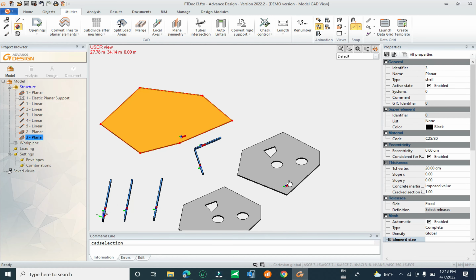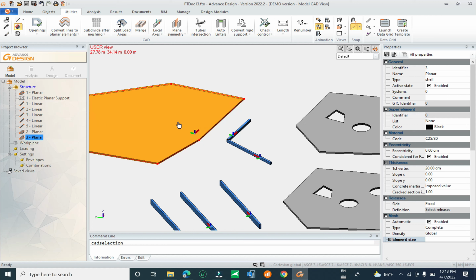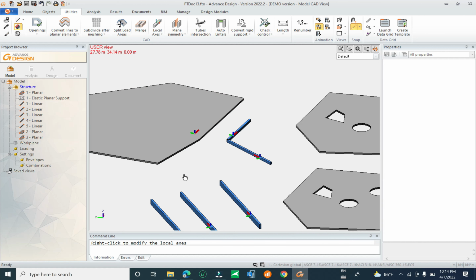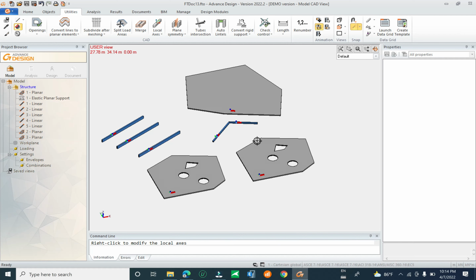Okay, in the same direction in x and z: local RC x, local RC z, local RC x, local RC z, and local RC y. It is the best practice when you analyze the complete model, or there are two or more elements in the same model. You have to make everything the same. It is easy to analyze and to design, and also easy to make a structural report when you output the rebar, the internal force, and for other analysis. It is a very good concept to apply when you are modeling.